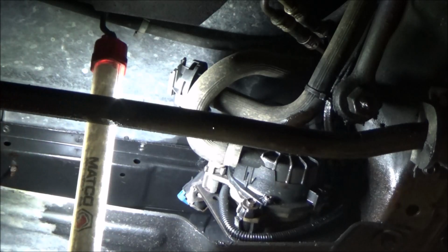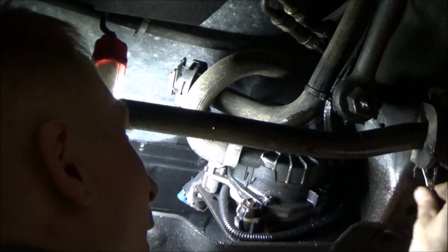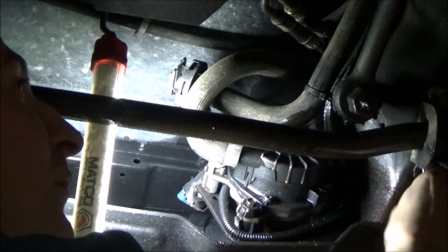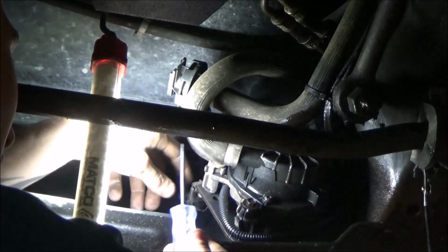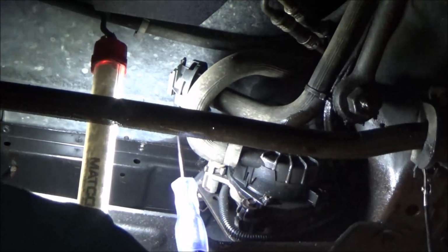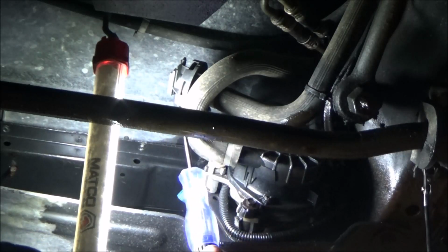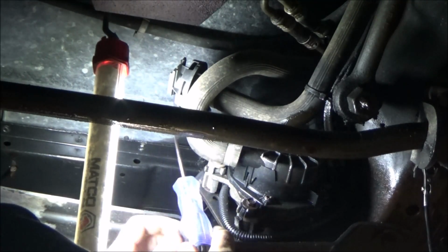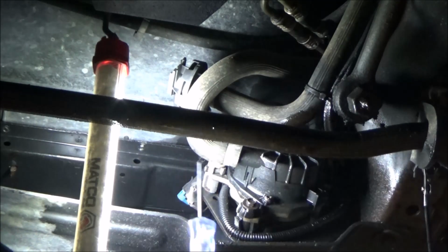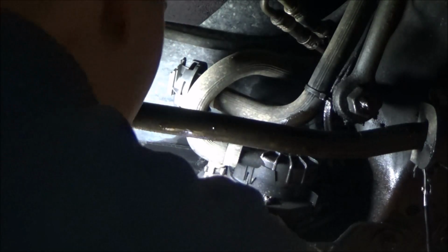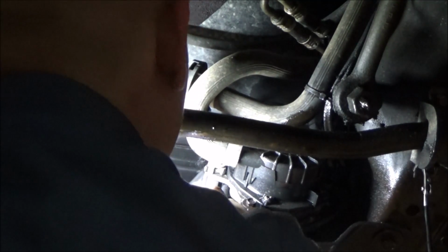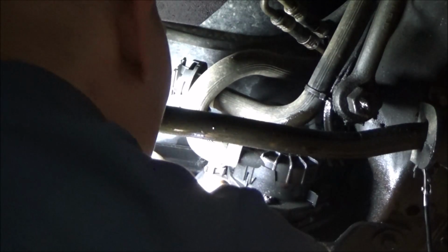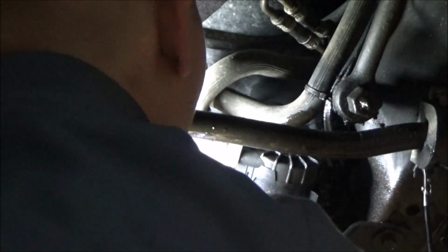What I may end up having to do, if we do not have anything on this solenoid down here, is run my lead up to the battery itself. So not sure yet, but all I'm going to do for this, guys, is use this test light, which is somewhat special. I probably wouldn't do this with a normal test light, but I have a 3425 bulb in this that draws about 1 amp of current, and I use this primarily for unplugged, semi-loaded circuit testing. I'm going to use that for this solenoid. The solenoid is not computer controlled, guys. It comes directly off of a relay, so I'm not worried about hurting this solenoid.